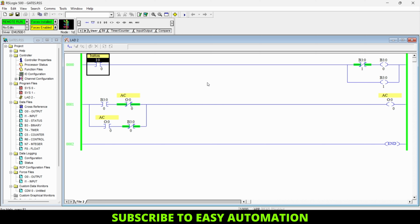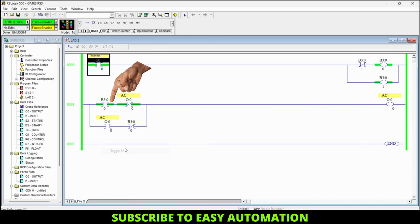Now I will explain how this output is going high and low using that trigger pulse. The trigger pulse is generated, and that trigger pulse will turn this NO contact to NC, and by making this contact NC, the supply will go through this and this NC contact as well. This NC contact is still NC because the output is not on yet. Whenever the output goes on, this NC contact will become NO. But now our output is off, so the supply will go through this NC contact to our output, and then our output will go high. As the output goes high, this NC contact will become NO, and this NO contact will become NC, which will create a holding.